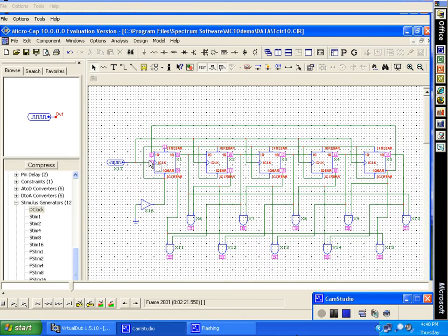This is the one that we're going to have to build. We take and look at the 1 of this flip-flop and the 0 of that. That decodes the 1. Similar here, 1, 0, that decodes 2. 1, 0 decodes 3. 1, 0 decodes 4. 1 and 0, 1 and 1 decodes 5. Over here we have 0 and 1 decodes 6. 0 and 1 decodes 7. 0 and 1 decodes 8. 0 and 1 decodes 9. And 0 and 0 decodes 10. So you see what we're going to construct.